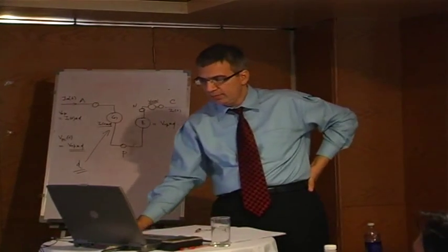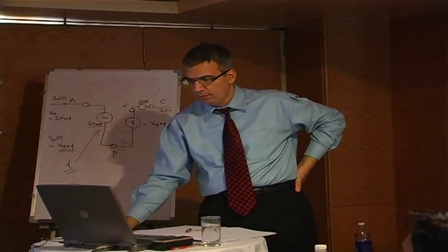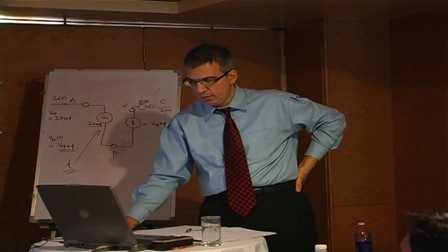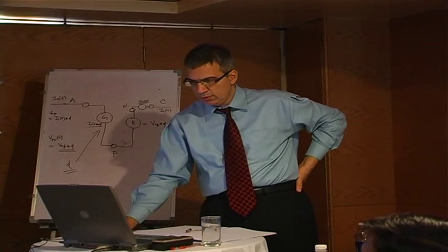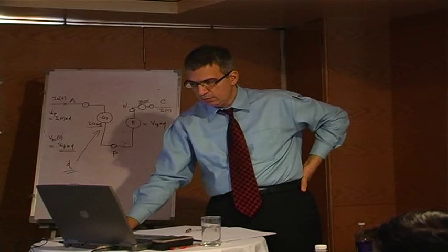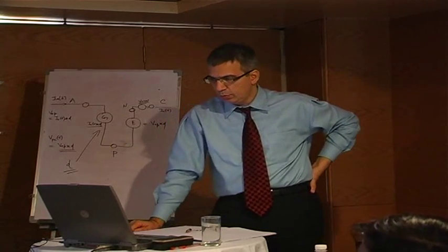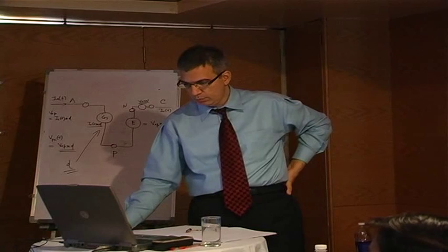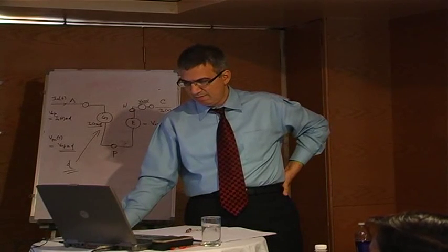So you have, what is the lowest voltage that you have here? See, the lowest voltage we have here on the diode, it's about 3.3. Something is wrong with the diode parameters. Yeah, it should be like 0.6 or 0.7.